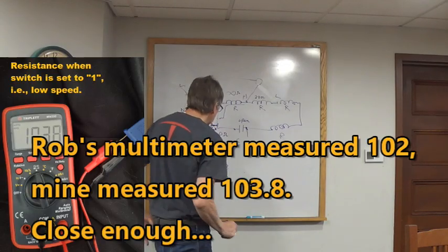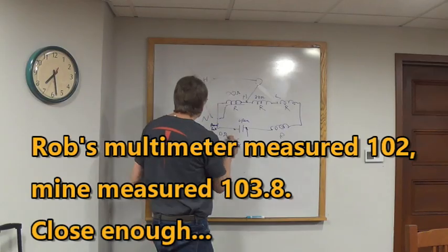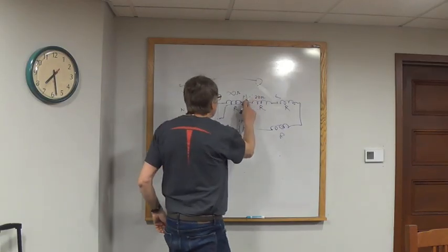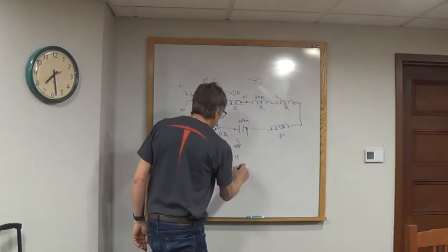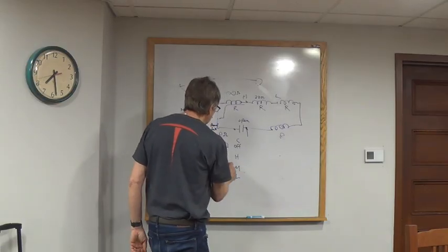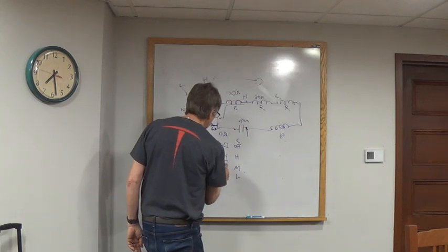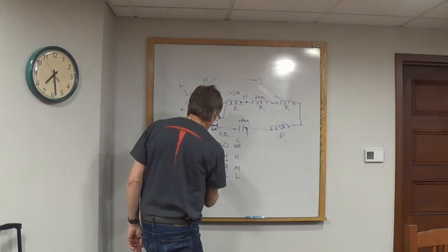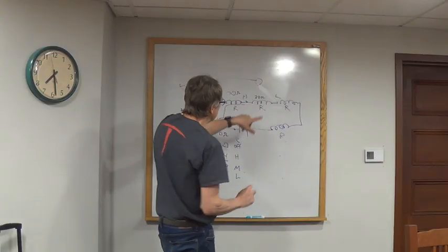All right. So this is off, when your switch isn't connected to anything. This is high, medium, and low. Notice that the difference between this and this is about 14 ohms, and the difference between here and here is also 14 ohms. Actually I only drew 2 speeds, but I've added a third.